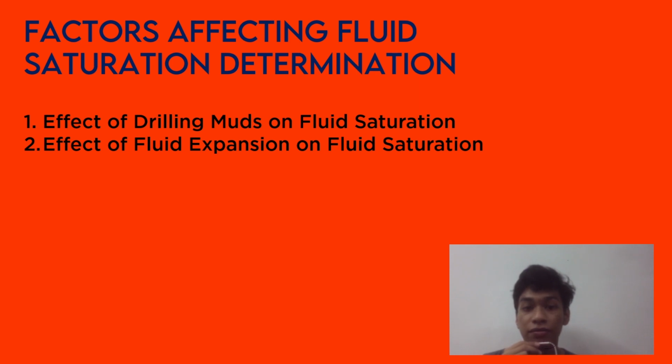So it might give a big difference in fluid saturation of the reservoir itself. So we can conclude that these pressure and temperature effects result in completely altered fluid saturation in the core sample as compared to the actual reservoir. Hence, fluid saturation measured in a core sample at the surface condition does not necessarily reflect the true saturation that exists in the reservoir. That's it.